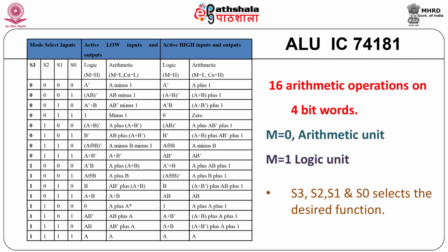In addition, there are 2 additional lines, carry in and carry out, which are provided for cascading and generating n numbers of ALU. The device also provides internal carry look ahead and provides either ripple carry between the devices, which is represented as Cn plus 4 output. For carry look ahead between multiple ALUs, a single carry propagate P and carry generate outputs are normally used.